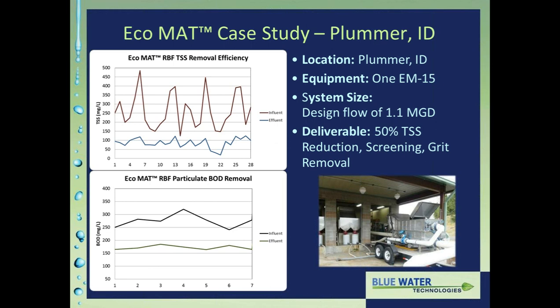But basically what the owner of the plant has to do on a daily basis is get up on a ladder, which you see tucked away just behind this column here. They have to get up on this ladder with a high-pressure hot water wash system and manually spray those screens down every single day.